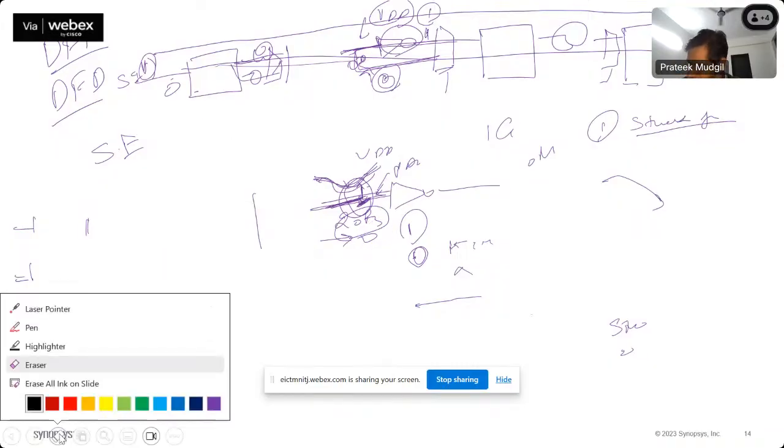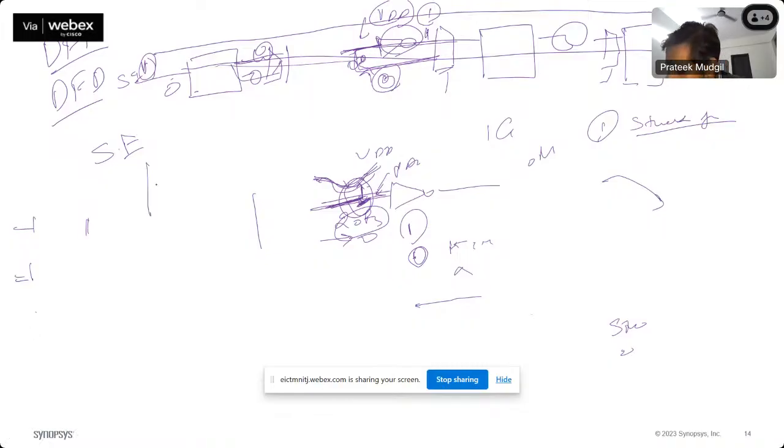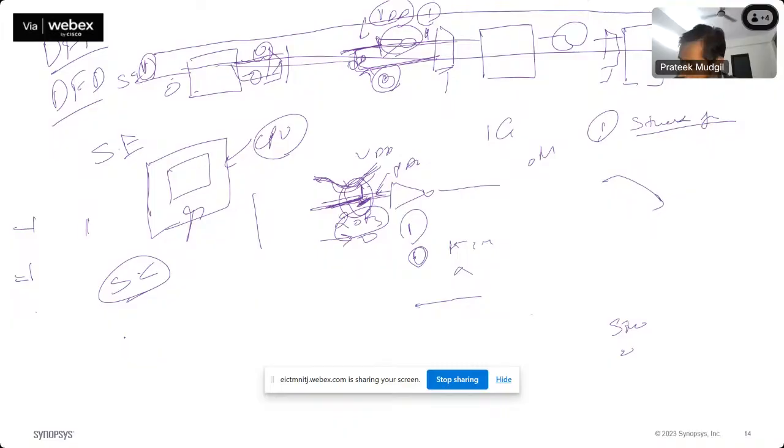So what happens, right? Let us say this is a CPU and we want to debug it. There is some issue, right? So what we'll do, we will bring the CPU in scan mode, right? And stop the clock, freeze the clock at that event. But this is again a debug mode, because scan testing doesn't have an option of freezing the clock and tracing it, right? So what we do, we freeze the clock.